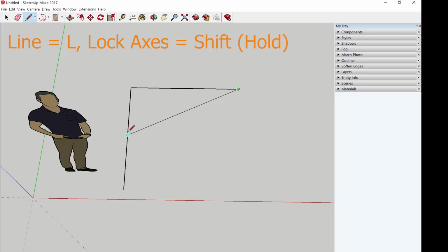So we know that this line was following the green axis. Once it's on the green, you hold on to shift. Then you tell the line that you want it to end with respect to this point. And you press left click, yes. Then as you're finishing, you come to the end point, and this is what happens. When you complete the lines, a square is formed, and in between there will be a face.